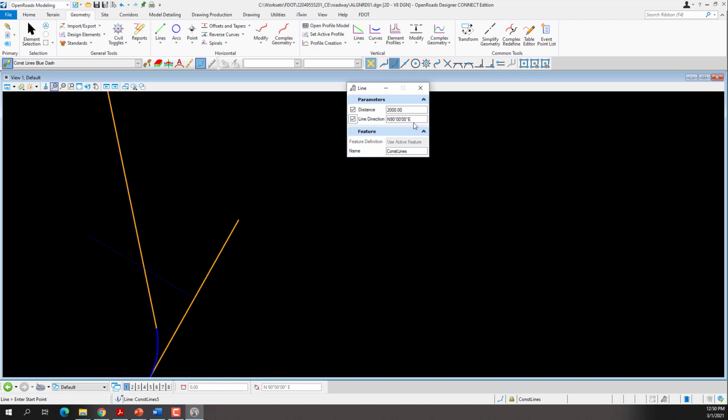And for our copy of the bearing, we do Control V as in Victor and paste that in. But we want to make one change before we place this line. Where the 11 is, we select that and make that 10, because if you remember from the beginning of the chapter, we wanted a 1 degree difference between these. And we're going to give this construction line 4.